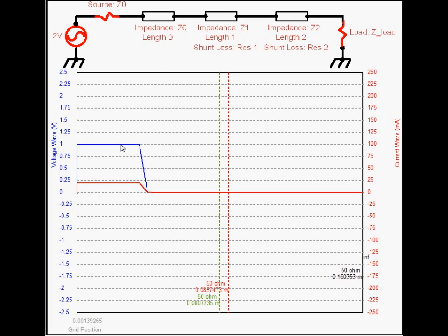It's still a voltage to current relationship that has to do with the waves as they travel down. But it doesn't necessarily mean that in the steady state case you'll have that same relationship, because fundamentally, with a coax or microstrip line, you still have just a 0 or very low resistance conductor going through for the signal, plus you have some ground return that's a low impedance, low resistance state.